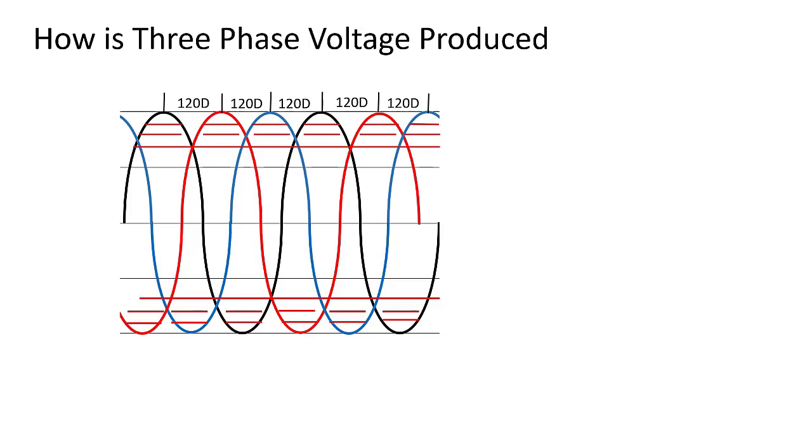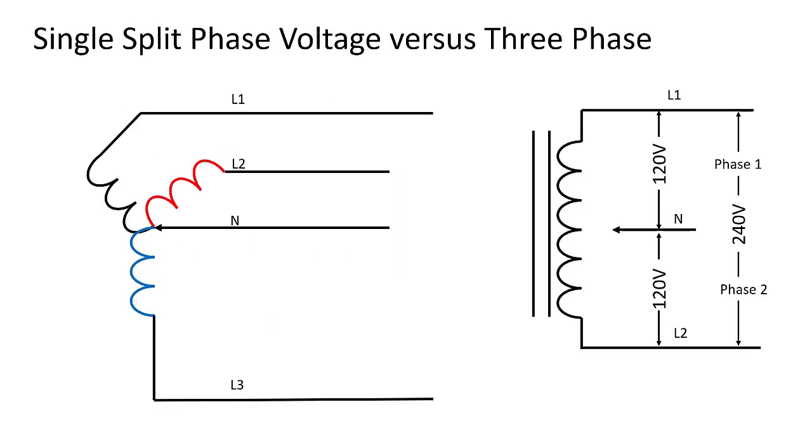Three-phase power is preferred by electric companies because it allows for certain benefits not attainable through other delivery methods. There is no need for a neutral line in a three-phase delivery system. This is because each of the three phases is carrying the exact same amount of current, which results in a linear balanced load. This allows the generators to work with more efficiency and less vibration. Three-phase power supply requires less conductors or wire material than single or split-phase delivery systems. The same amount of electricity can be delivered in a much more economical fashion.